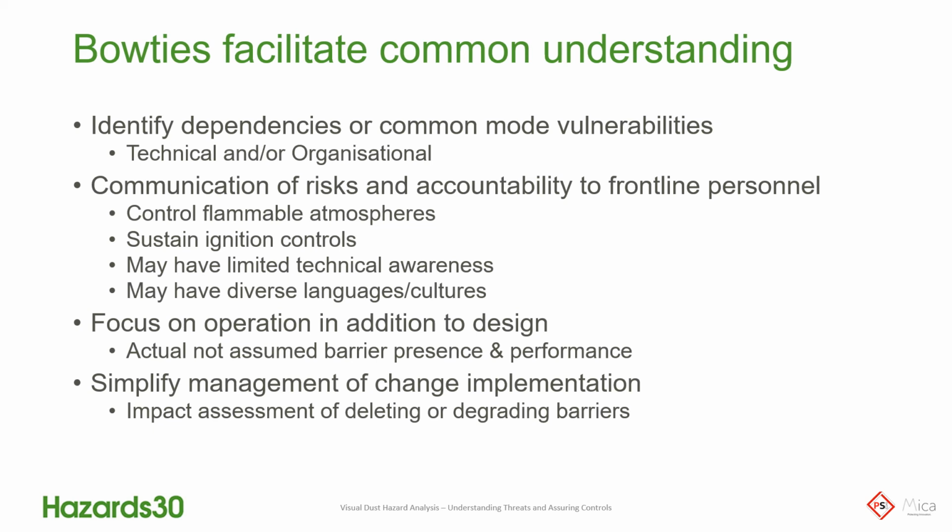You can communicate the risks much better to frontline personnel, how they are going to control the flammable atmospheres, how they are going to, through operation and maintenance, sustain those ignition controls or avoid the ignition, because the frontline personnel may not be chemical engineers, they have limited technical awareness, and in many countries you're relying on personnel who have different languages or different cultures.